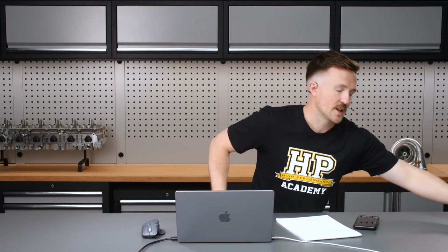The other one to consider around design for manufacturing, specifically with sheet metal parts, not related to bending, is the actual cutting process. So if they're CNC cut on a laser cutter, water jet cutter, or plasma cutter, all three of those methods have different DFM considerations. What I mean around this is things like the size of the diameter of a hole cut through a certain thickness of the material, for example.